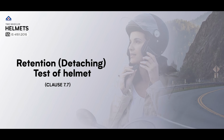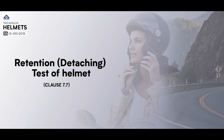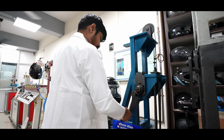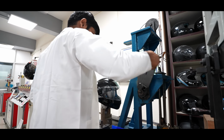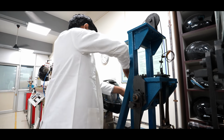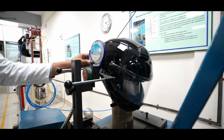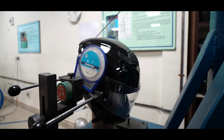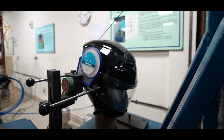Retention, detaching, test of helmet, Clause 7.7. The retention system test ensures that the angle between the reference line situated on the shell of the helmet and the reference line of the head form shall not exceed 30 degrees. A specified falling mass of 10 kg is applied and the angle should not exceed 30 degrees.